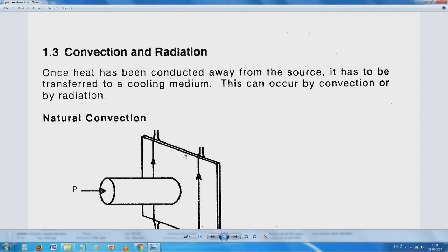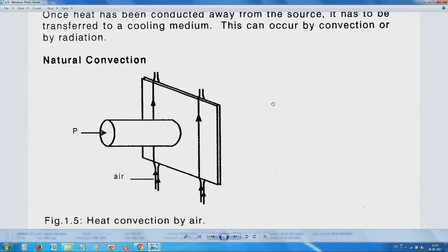Now, you need to pass it on to the cooling medium. I have given you an example of the circular tubes which are used in air conditioning and other things, where you can have radial fins inside and you can have radial fins outside. When you have these radial fins inside and outside, that behavior can be modeled easily. Now, in the case of heat sinks, similar modeling has been done here, saying you need to take away heat by convection.